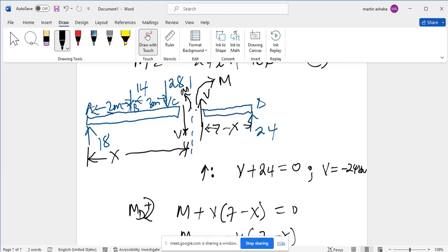Meaning that I can draw the portion of the beam from A to C, then I extend some portion. Remember, if this is C, then there is some portion continuing, showing us that we are analyzing between C and D. Then the other part is moving from where we cut to D. So if I indicate my internal forces or internal loads, the bending moment and the shear force within that beam or that section, I indicate the proper sign convention on this other side, on the left side.